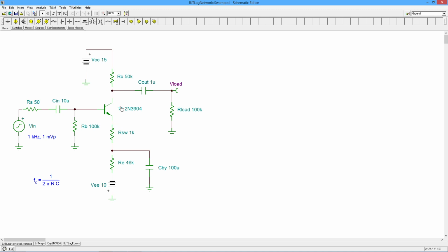All right, we're going to need that a little later, so remember that. We need about 6 volts from collector to emitter. We can also figure out the gain. Given the current of about 0.2 mA, we would divide that into the 26 millivolt constant for r'e. So 26 millivolts divided by the 0.2 mA gives us about 130 ohms. So our gain would be the AC value of RC, or 50K in parallel with 100K for 33 1/3 K, divided by the swamping resistor of 1K plus the r'e of 130. And we'll be looking at a gain of about 29 or so.